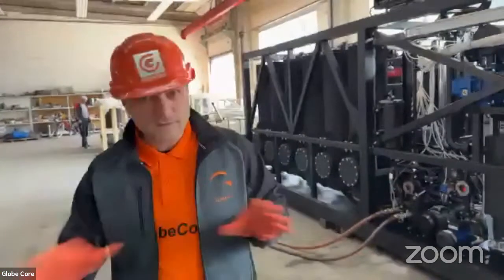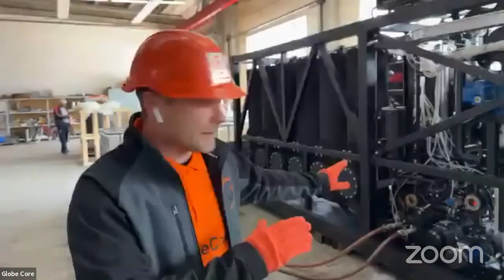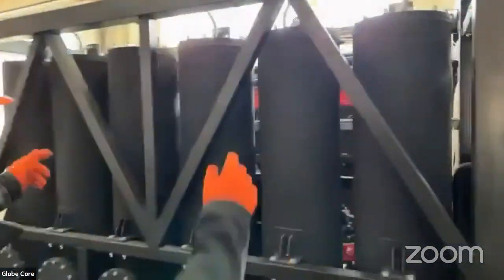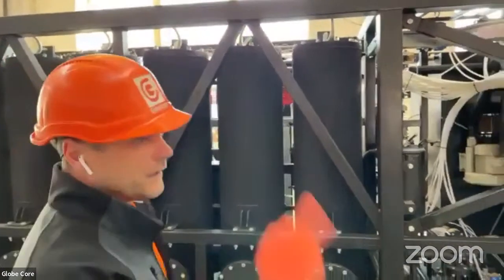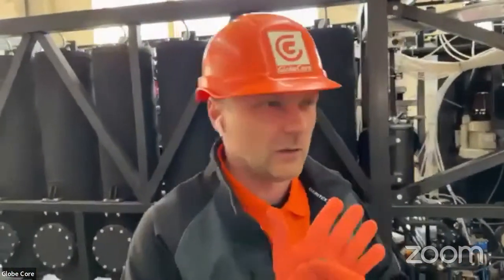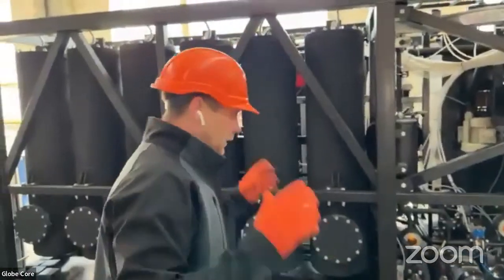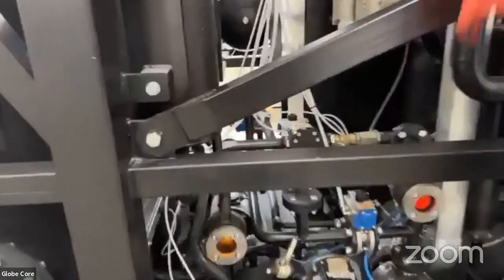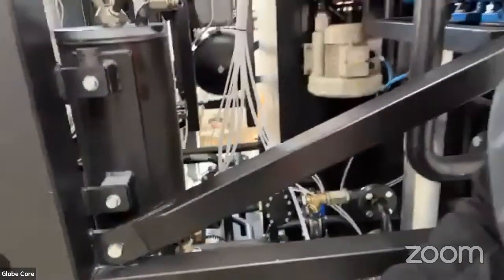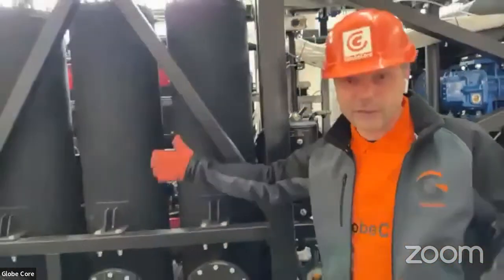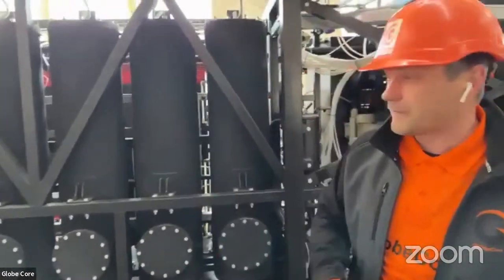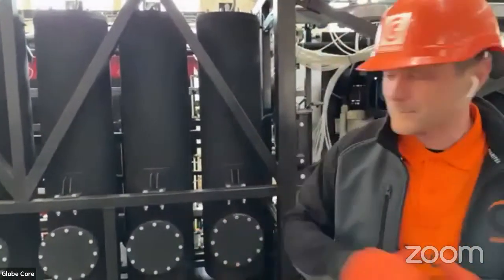First of all, the same principles are implemented in here. Literally, we have columns in here. So altogether, it is 12 columns. Each column has 150 kilos of fuller's earth again. We have, again, the gear pump, the inlet gear pumps. You can see it is actually on now. The unit is under testing, and at the same moment, we perform the regeneration of transformer oil for local clients.